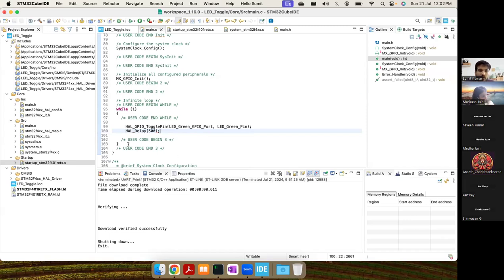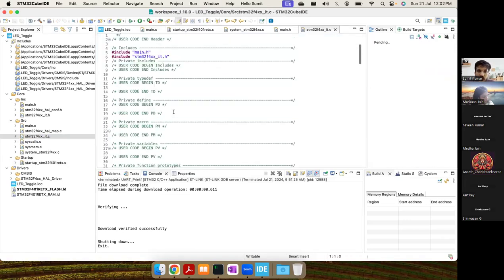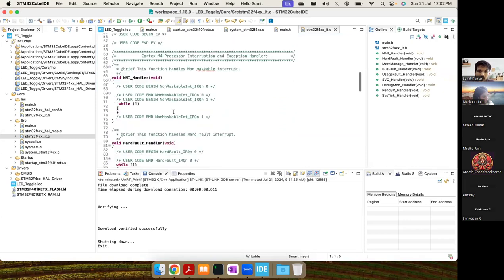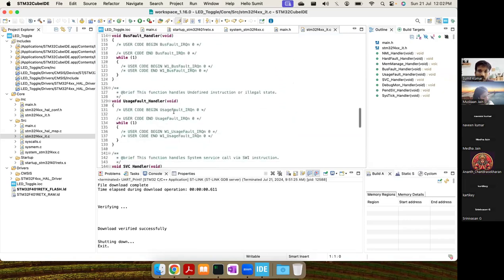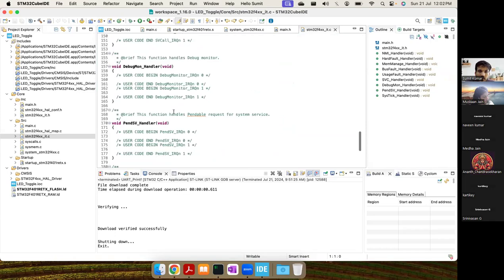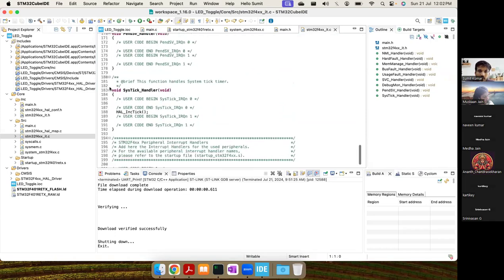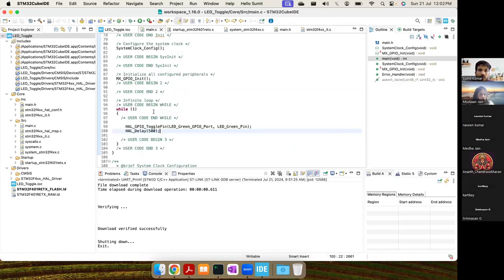Save it. I will just quickly check in it.c if we have the SysTick defined. Okay, so we have the SysTick defined, so our HAL delay will be working. So the code is ready.